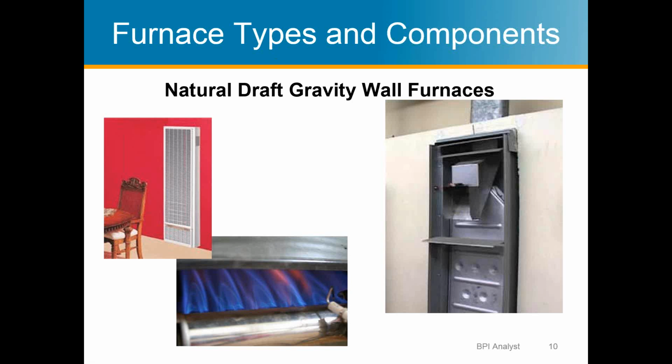So when you make homes more energy efficient, put new windows in, add insulation, do air sealing, you typically make all natural draft appliances more risky. That's the reason why we do a test out on these as well.